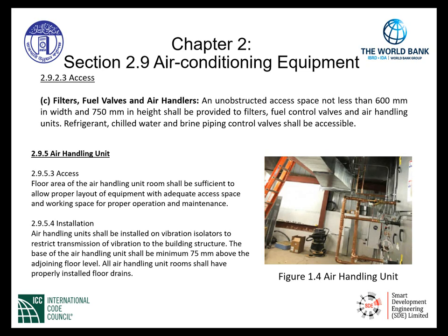In other words, we need to elevate the equipment accordingly for corrosion protection, allowing air to move underneath the appliance, and for cleaning purposes as well in the mechanical room, such that there is a space underneath the air handler.